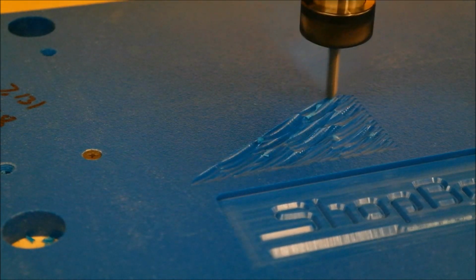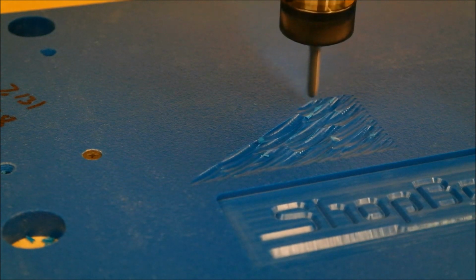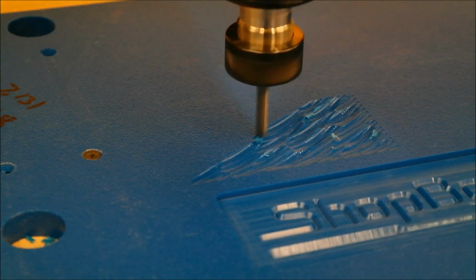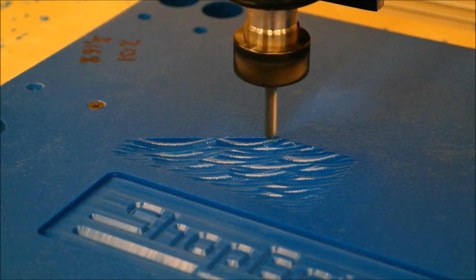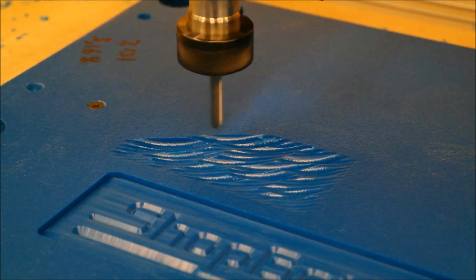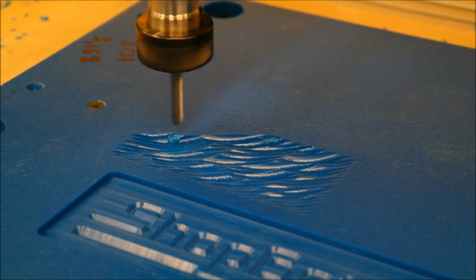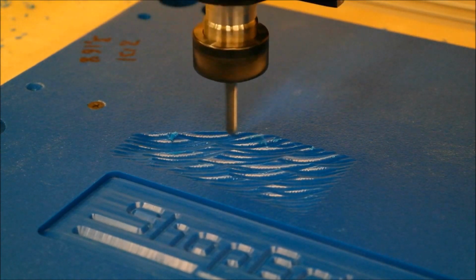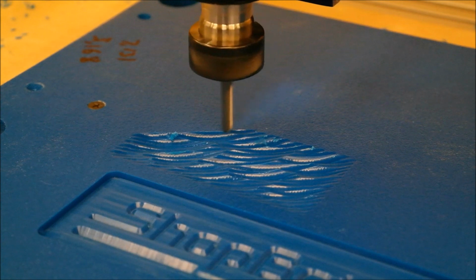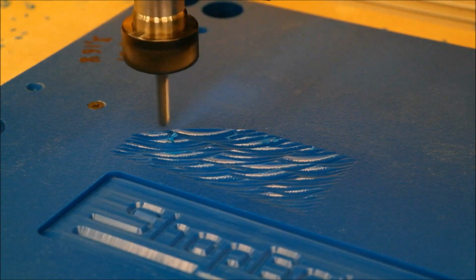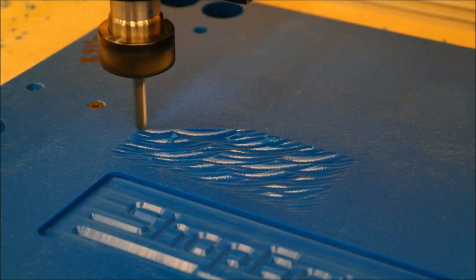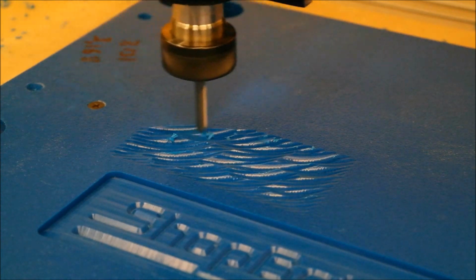Again, without really zooming in, you can see there is a little bit of material that's left. So I will tell you that with the texturing toolpath, just with the step overs, sometimes there is a little bit of sanding required. It's not much. If you have a little slap wheel on, say, a Dremel, that'll get any of those little burrs or furries that you have left over. But simply enough, there's the texture toolpath.